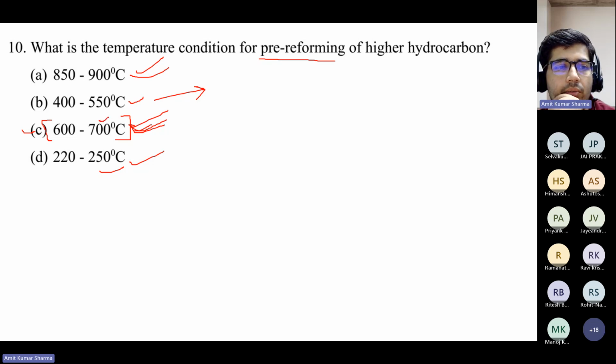and also the 700 degrees. No, it cannot. For methane cracking, that will be more than 700, I think. Yeah. But it's still not advisable. So this one, the medium temperature of 400 to 550, is for pre-reforming, and then you can use the reforming temperature.